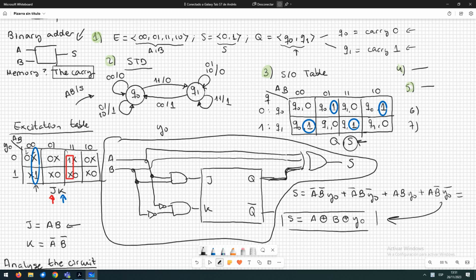The sequential circuit, the memory element, is going to work with a clock. So imagine that we are working with, for example, a JK bistable triggered by rising edge. So triggered by the rising edge, this was the symbol. So we have here the clock of the bistable. And you cannot forget this, because if you forget the clock, the circuit doesn't work.